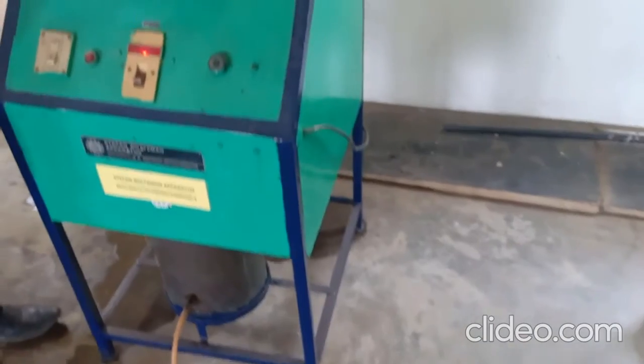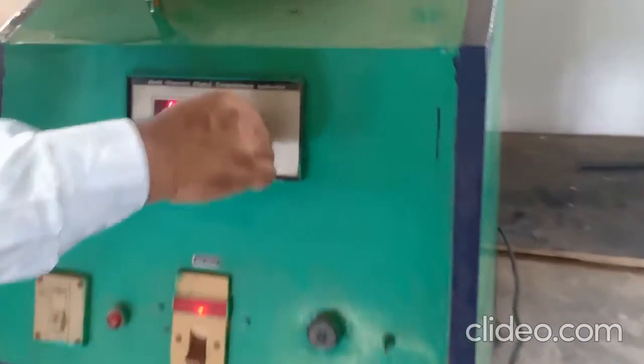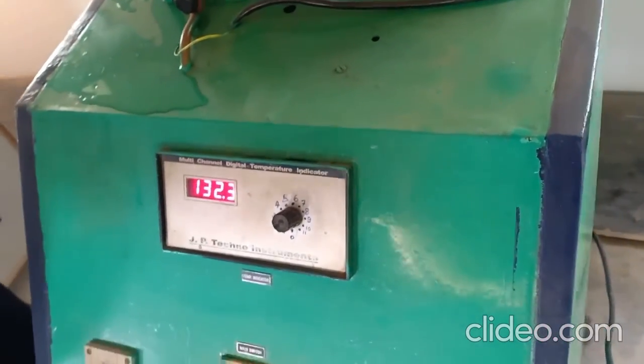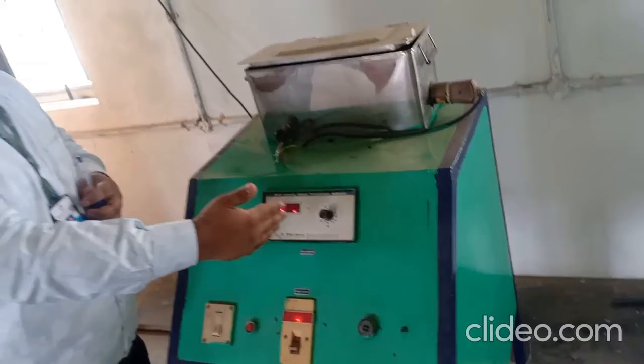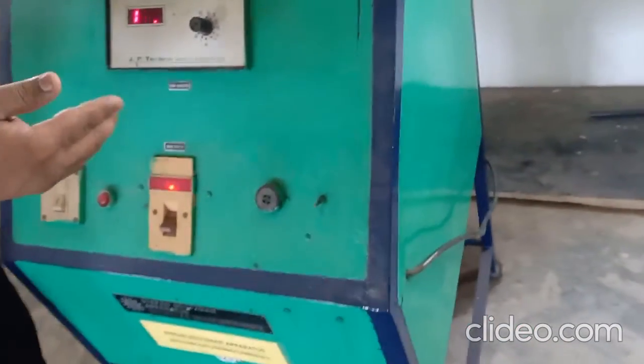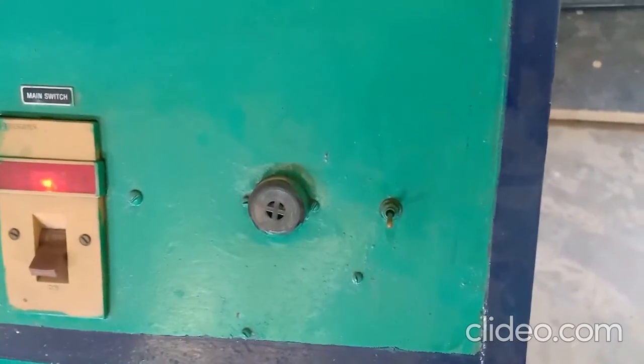Here the temperature readings are T1, T2, T3, T4, T5. We are going to take down these readings as is. Once you get the steady state condition, you have to take a set of readings for different time intervals. The beeper is sounding because at every beep we have to take the test readings.